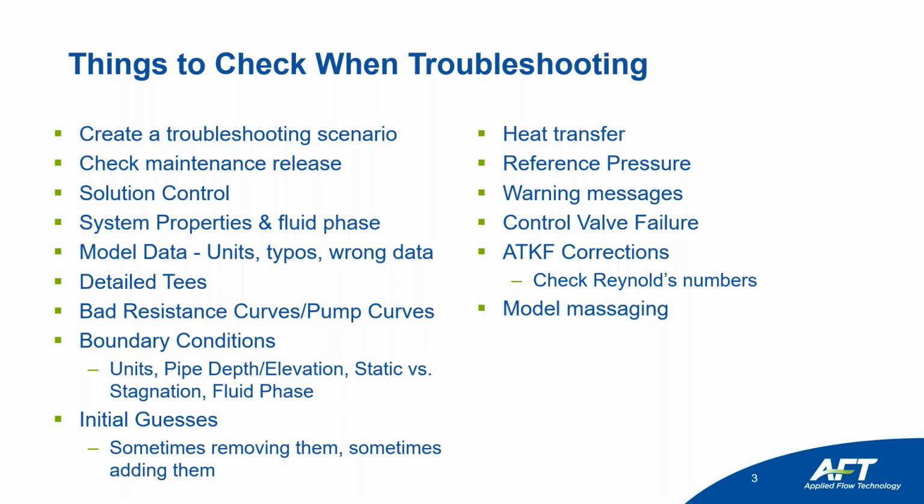Another point where this is helpful is if you have a very complex model with lots of branching or lots of looping. With all those branches and loops, it could get difficult for the model to be able to solve, especially if your flow distributions are very similar. So a technique is to shut off several flow paths and just have a single flow path turned on, run your model, get convergence, transfer results to initial guesses, and then turn on other additional flow paths, and that way you'll be able to get convergence over a series of iterations.